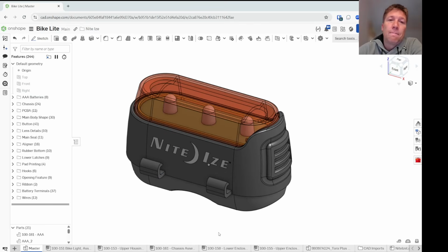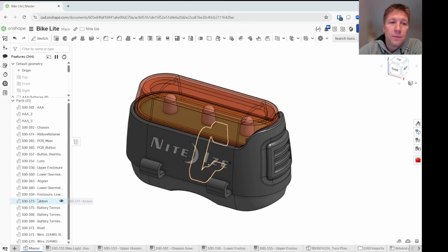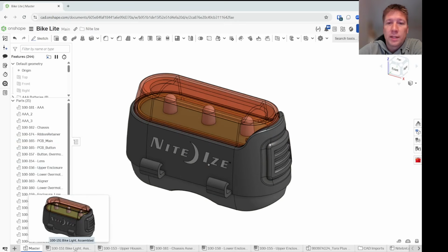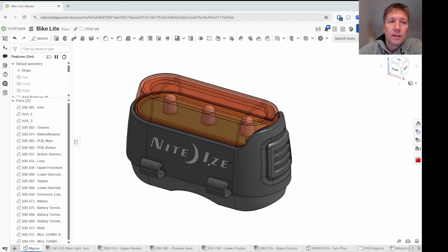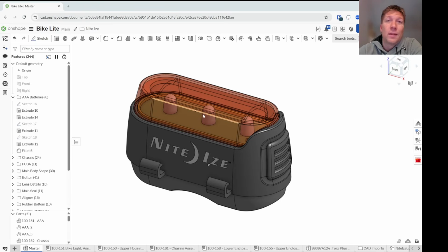What that means is I am looking at the assembly as though it's a series of parts. There's actually 21 bodies in my part file, and then I expand those out into assemblies and individual part files for further detailing. This works well when your assembly is lightweight. This I'd consider lightweight. It's fairly complex, we have 21 bodies here, but almost every part needs to know some information about another part in order to exist. This would be very difficult to build if you tried to build each of these parts independently.